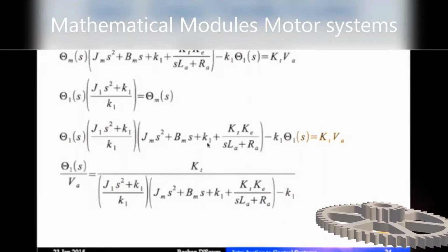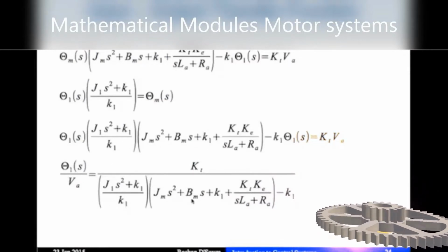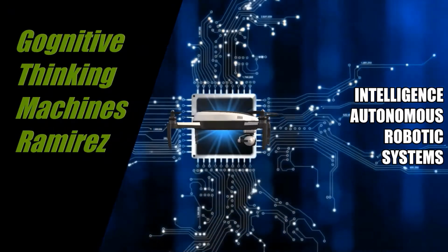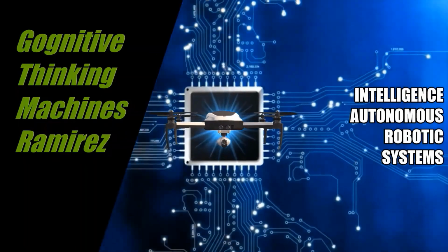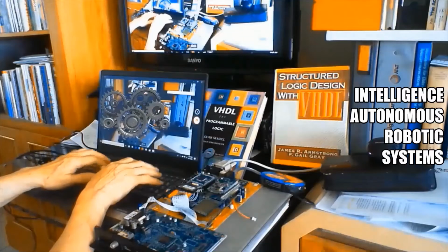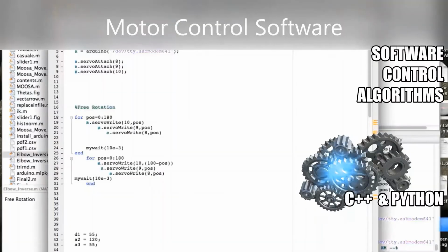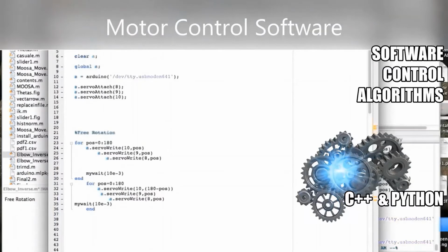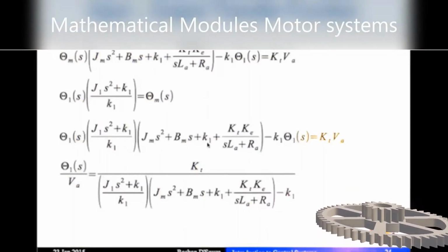That is, the direction, yaw, vertical inclination, pitch, and horizontal inclination, roll, and altitude of the drone are all controlled by manipulating the velocity of the motors with respect to each other and to the force of gravity. When all four motors rotate at the same speed, the drone autonomous system can move up or down or hover.